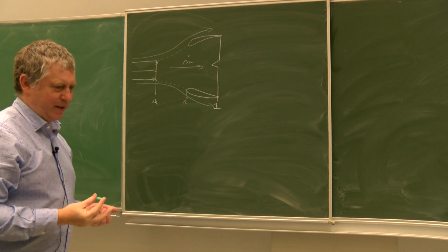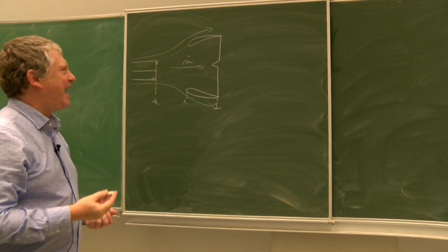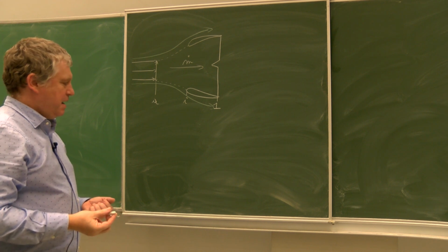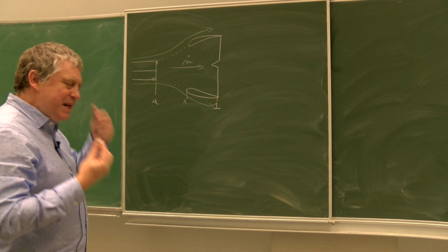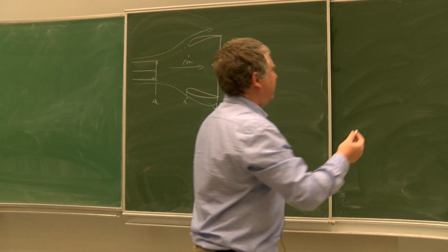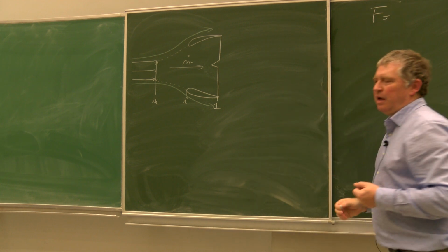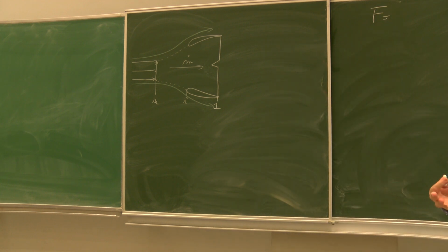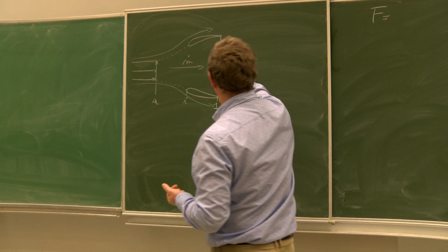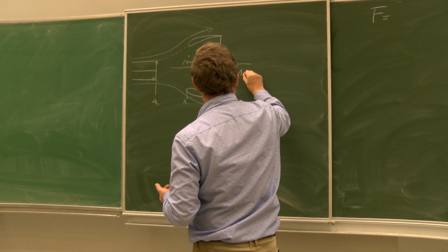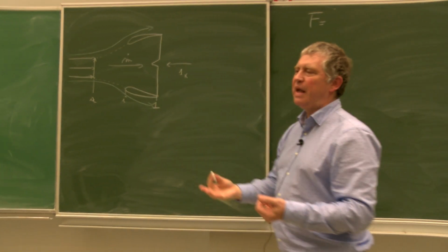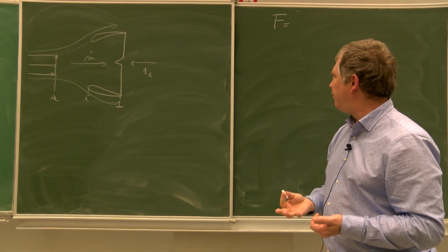And we are interested in the study of this external flow because of the equation of the thrust. Let's consider that the thrust is only along the axial direction of the engine, what we can call the direction X, the direction 1x that we have here, oriented, let's say, positively forward.